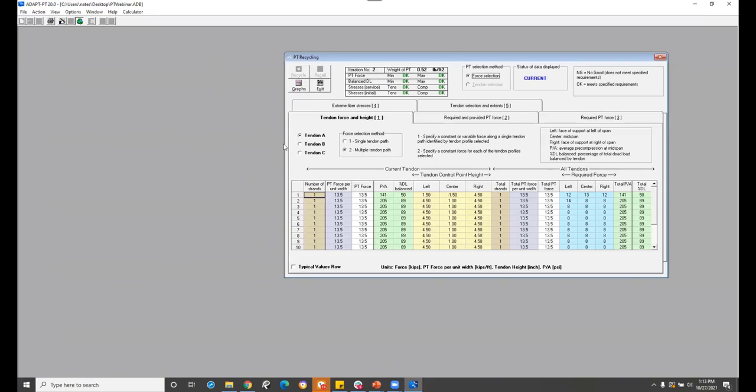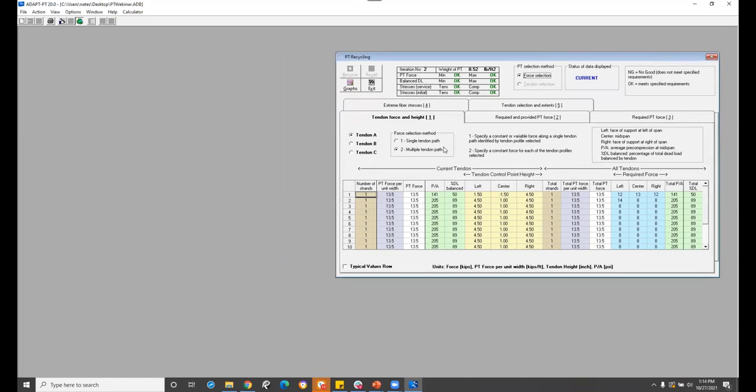Hopefully this gives us a more realistic or acceptable design. And as you can see, we're green okays on everything. And looking at this total pre-compression here, we're much lower. Obviously it's less because we have a thickening on that first span. So we could be done. We could say, yeah, this design's okay. We can just run with this. But with my experience, I'm going to see if I can optimize this a little bit more.